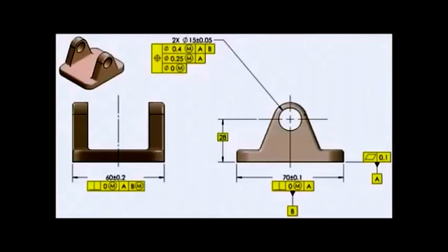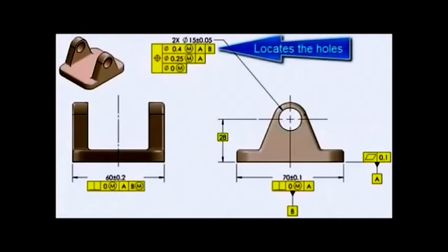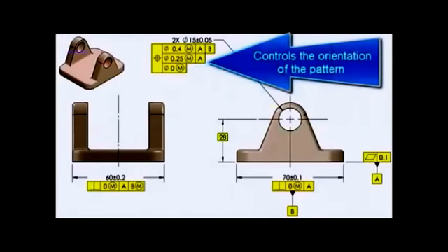The composite tolerance on this drawing was explained in the May 2012 tip. The upper segment locates these 2 holes. The lowest segment is controlling the relationship of the holes to one another. This middle segment is the one that will be illustrated in the gauge.